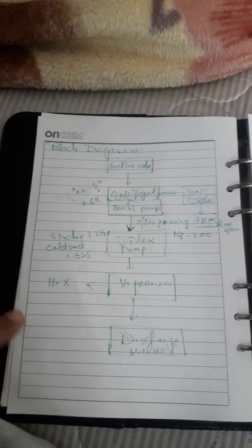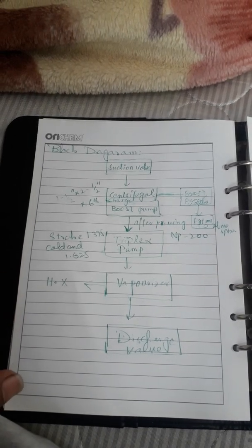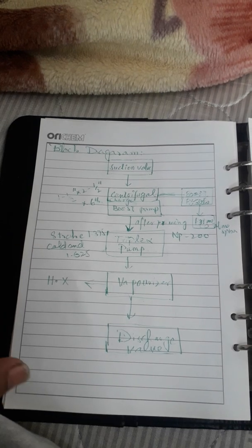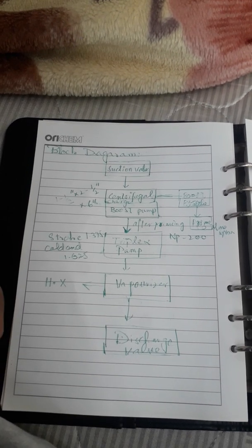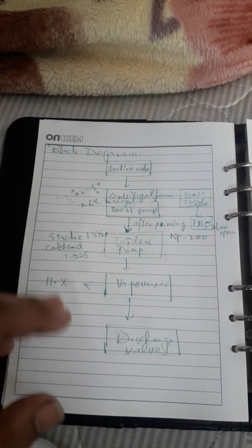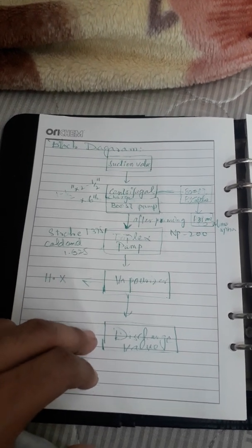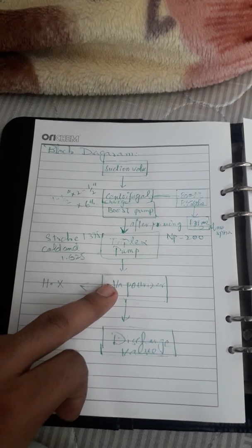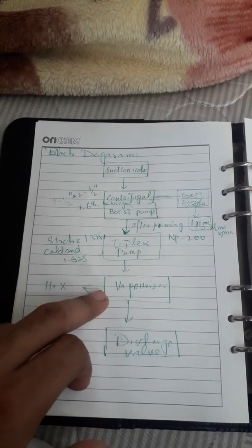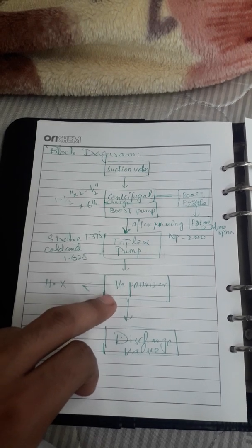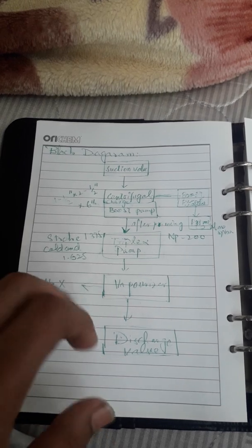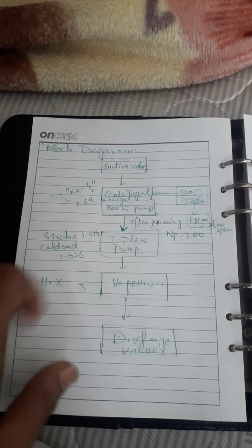When the engine coolant system comes, it extracts the heat from the hydraulic oil system. After that the lube oil system and a series of heat exchangers, then it comes into the vaporizer. Here it will extract the heat, and all the heat is given to this liquid nitrogen, and after that the coolant's temperature is cooled, and it goes back to its circuits.